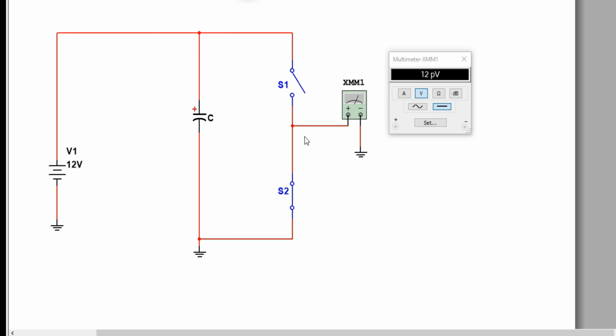As we discussed in the lecture, at a time only one switch is active while the other switch is deactive. In this case, I have used these SPST switches in place of IGBTs. These are working the same as IGBTs. Switch closed means IGBT is active, while switch open means the electronic switch IGBT is in open state or deactive.